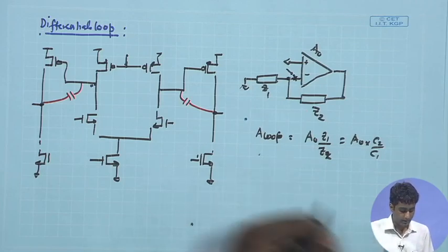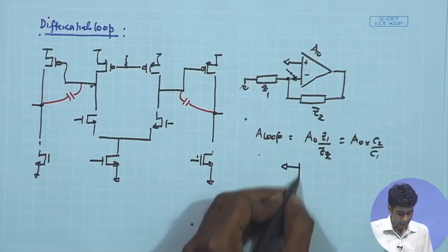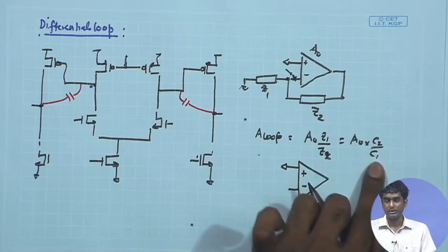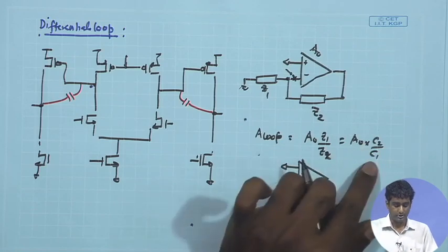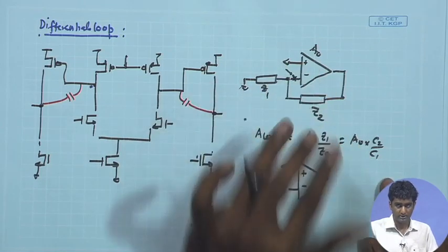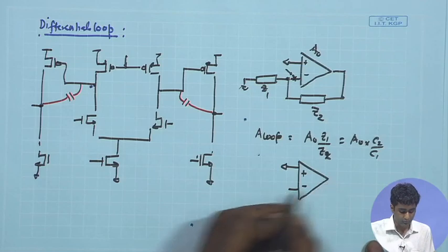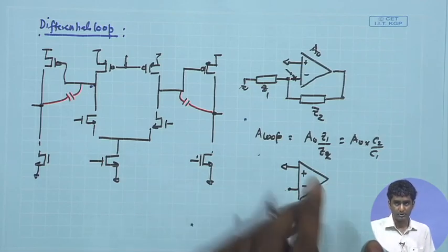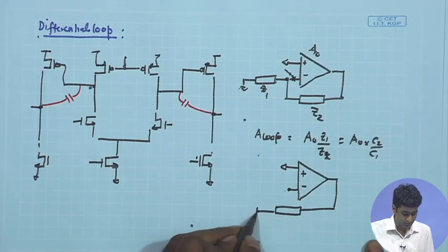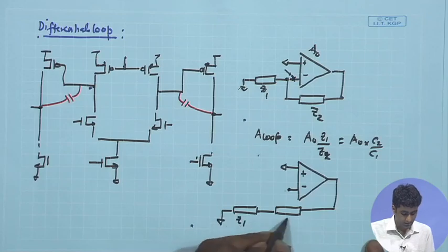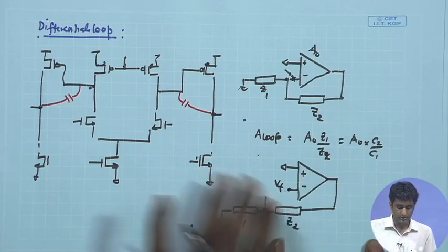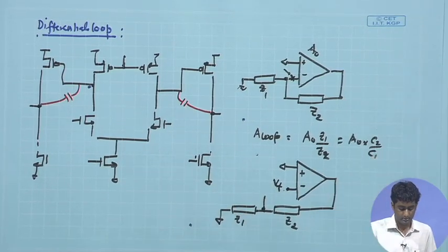So, we can open the loop and first of all confirm that yes, the loop gain is the same as what we expected using the shunt topology that we arrived at. So, we had discussed the overall feedback topology that we are having, and we arrived at the loop gain. If you are opening the loop at this particular point at the negative input terminal of the op amp, and then looking at the final voltage signal coming over here, we need to be sure that yes, the overall transfer function between Vt and the feedback signal over here is similar to what we achieved earlier.